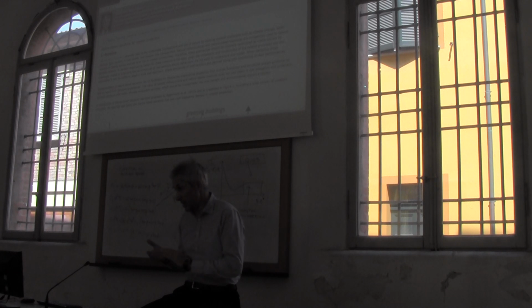As for any classification, once again, don't assume that there is a clear difference between structural interventions and nature-based solutions. For instance, if I talk about a groin, one would say that it's nature-based because it's natural material. And also, it's based on the development of an ecosystem, because inside the groin you have life that grows up and therefore protects the natural ecosystem of the beach.